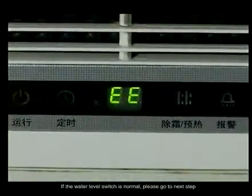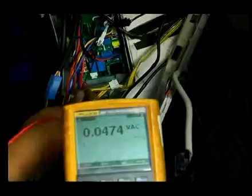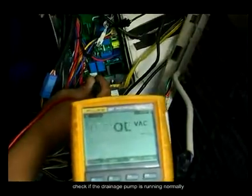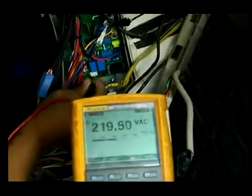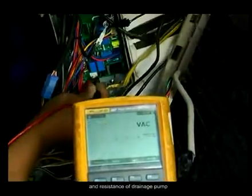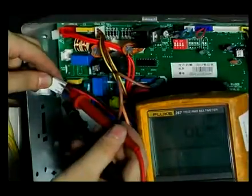If the water level switch is normal, please go to next step. Step 3. In the cooling operation condition, check if the drainage pump is running normally. Use the multimeter to check the power input voltage and resistance of drainage pump.